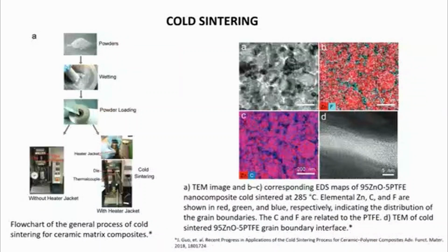Since its first introduction in 2016, cold sintering process has gained worldwide interest from the scientific community. A green and innovative fabrication route due to the dramatic reduction of processing time, energy, and cost. Cold sintering resembles the geological formation of rocks, where a ceramic powder is densified with the aid of a liquid phase under an intense external pressure and limited heating condition below 350 centigrade.